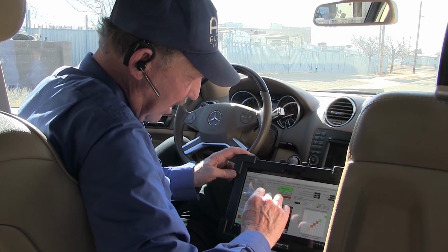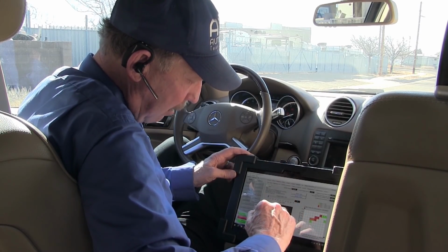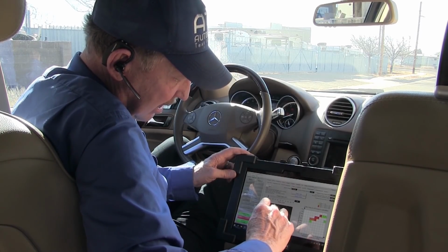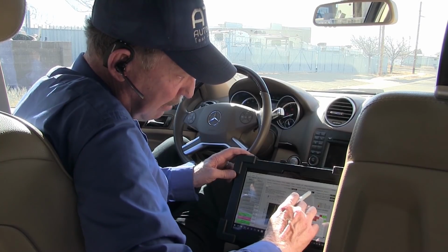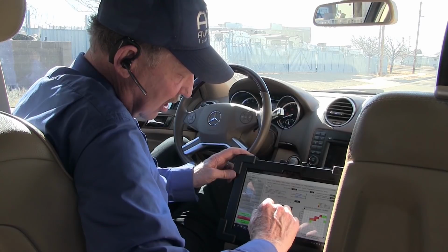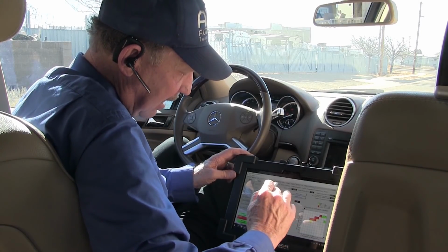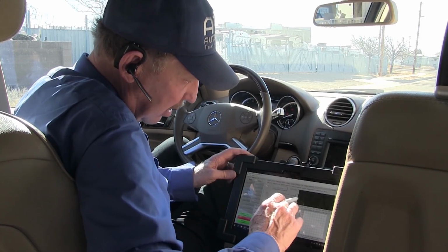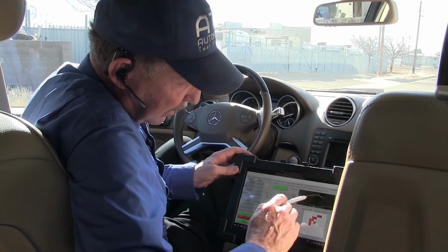If you're not sure about the VE, this is scaled, so this will read this engine correctly, but I always like to go to power, and then we're figuring the horsepower based on the air. And here we go. We can see that we came up and we made the horsepower that the factory says the motor can make by air, but it's not taking in the fuel control. This is just saying I pumped enough air to make the horsepower. So I'm pumping enough air and I read enough air by the VE. So now what I want to do is go to the compare table and run these two. Now I want to show you something.